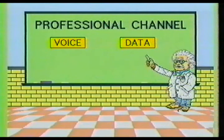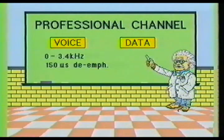The professional audio channel is used by the broadcaster for either voice or data communication. When audio modulates the professional channel, the audio frequency range will be from 0 to 3.4 kHz. A 150 microsecond de-emphasis is required when audio is used.